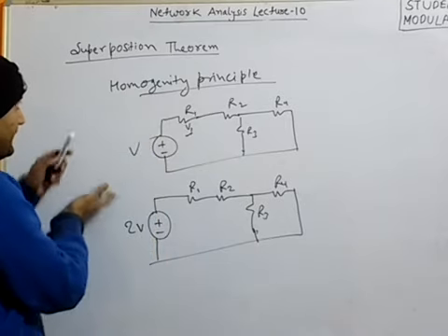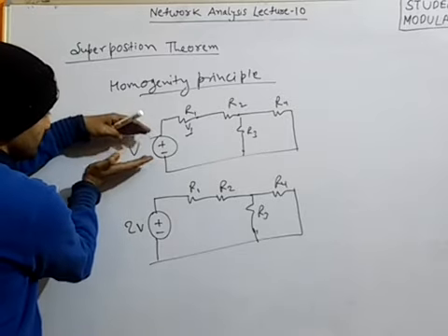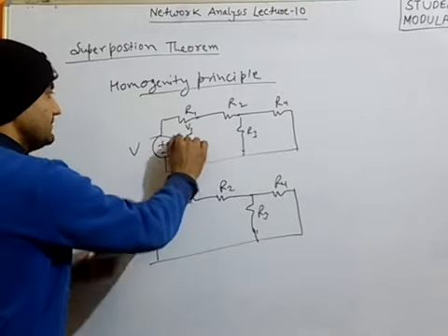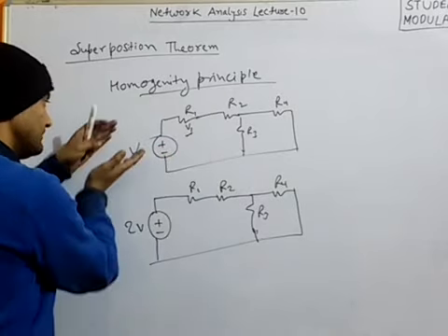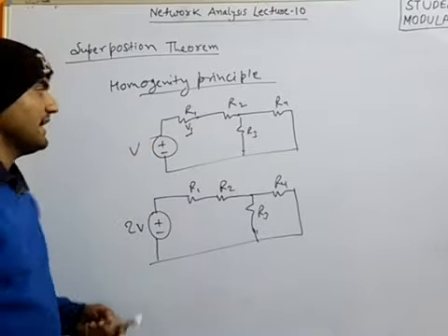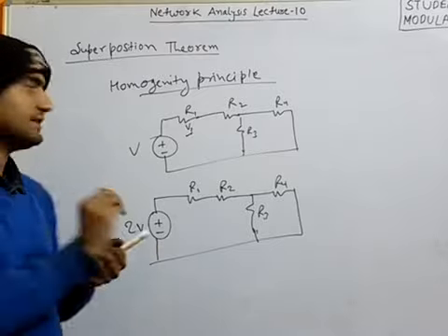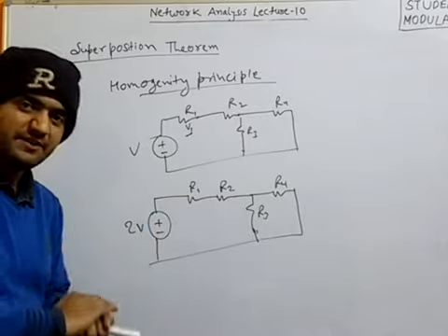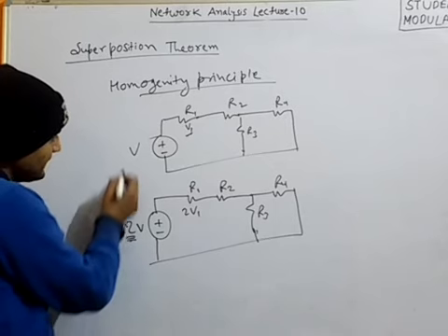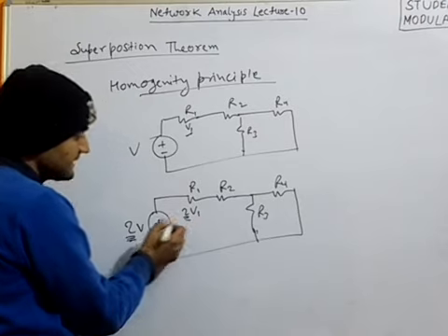And as per the superposition theorem, if two similar voltage sources are added here, due to one voltage source we have got the result V1. So due to the other, the same voltage source, we will get the result V1 again. And if we sum the two, V1 summed with V1 itself, then the result will of course be 2V1. Means when we scale the source by 2, the response is again scaled up by 2.